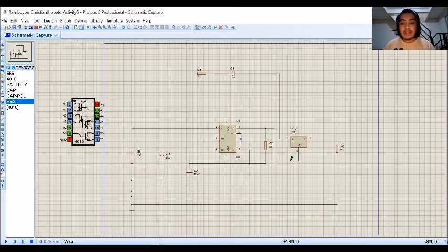The 4016 can also be called a quad bilateral switch. It has 4 bilateral switches that can be controlled independently using a digital signal. Each switch has 2 pins called SWX in and out, both of which can be used as input or output pin. They can also be used to switch variable voltages like PWM wave, sine wave, and others of low magnitude and frequency. These 2 pins will be controlled by the control X pin.